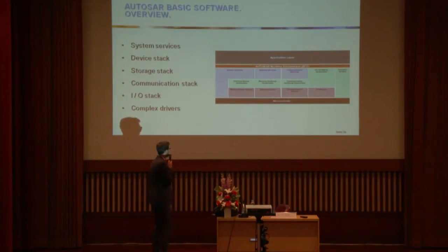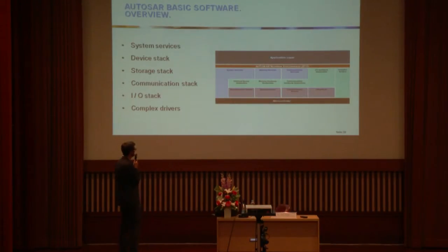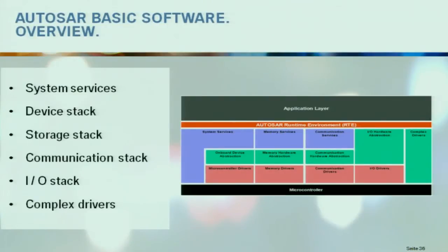So what we have seen in these pictures, we have several services, so-called stacks. This is one stack, this is the memory stack, the communication stack, and so on. And this is how AUTOSAR is built up. The system services does more or less things like scheduling, and gets all the microcontroller resources. The device stack provides or manages the additional devices, for example, watchdog devices or things like that.